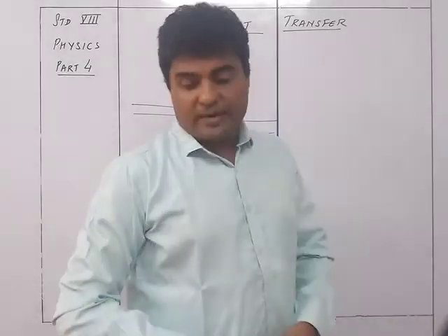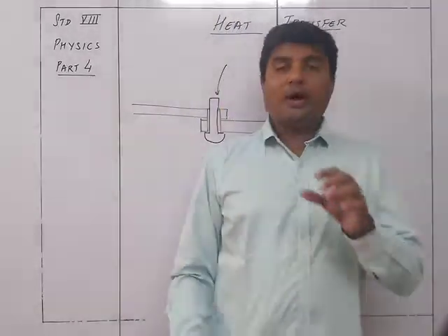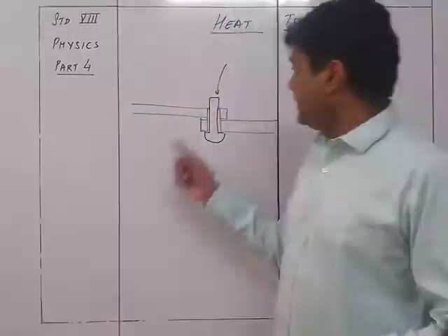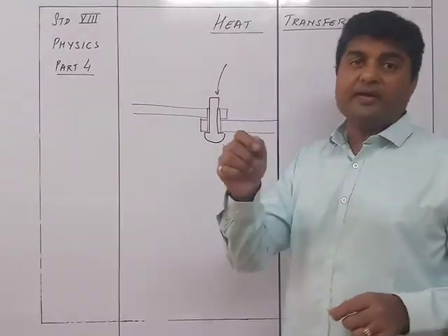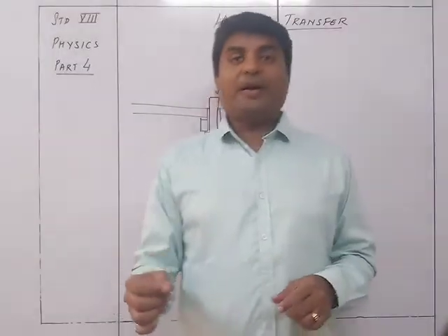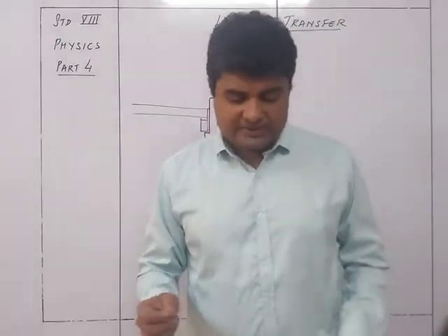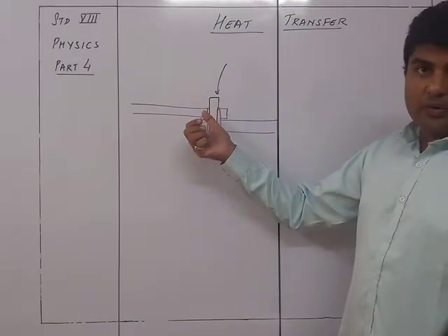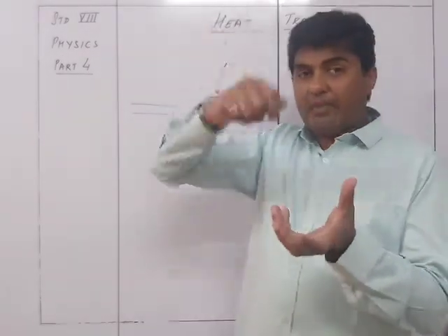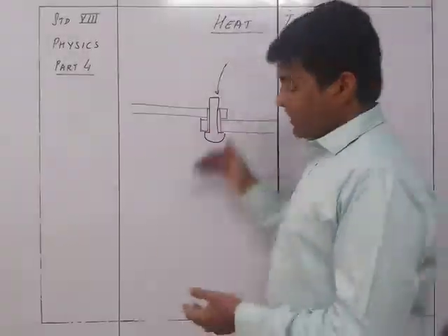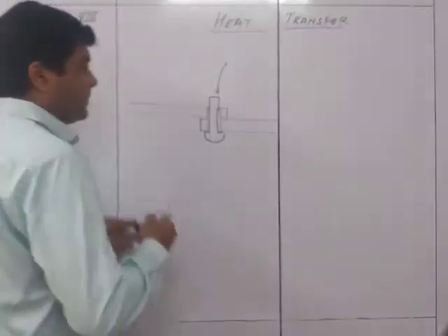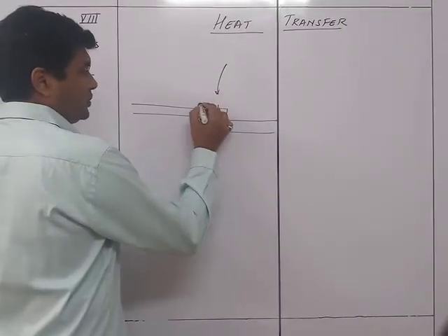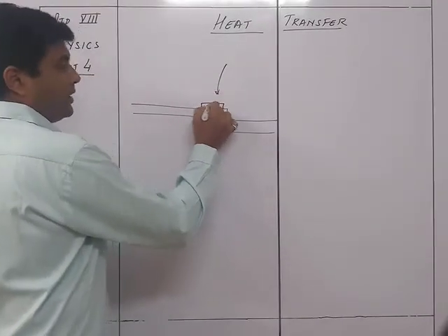But before hammering it, you are going to heat this rivet. The rivet is going to be heated. Now when it is heated, this red hot rivet is going to come over here and fit over here, and because it is hot, you can hammer it very easily. So you hammer it, and it is just going to become flat over here, like this.